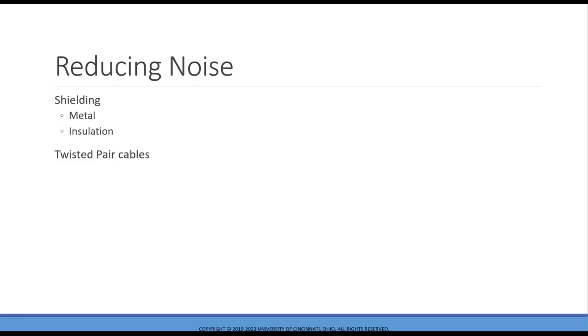Both man-made and natural sources generate noise. So whether the background radiation is naturally occurring or from man-made emissions, we must protect our data communication from electromagnetic radiation. One way to reduce interference from noise is to place metal between a source of noise and a communication medium. Because metal absorbs radiation, it acts as a shield, so if there is enough metal placed between the source of a noise and communication medium, it can prevent noise from interfering.